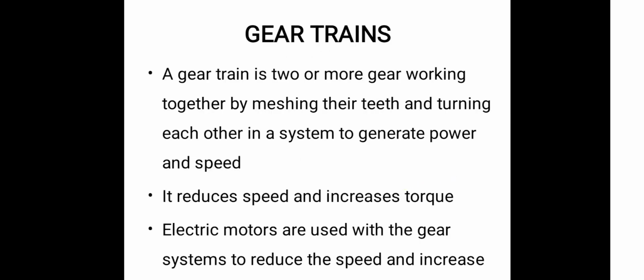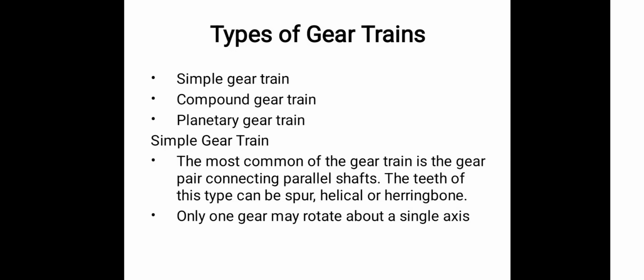Gear trains: more than two gears and shafts that we utilize to transmit power are called gear trains, which are used to transmit power over long distances as well as for great reduction of speed. Gear trains can be classified into simple gear trains, compound gear trains, and planetary gear trains. A simple gear train transmits from one shaft to another shaft, and gives only a small reduction of velocity ratio as well as torque reduction.